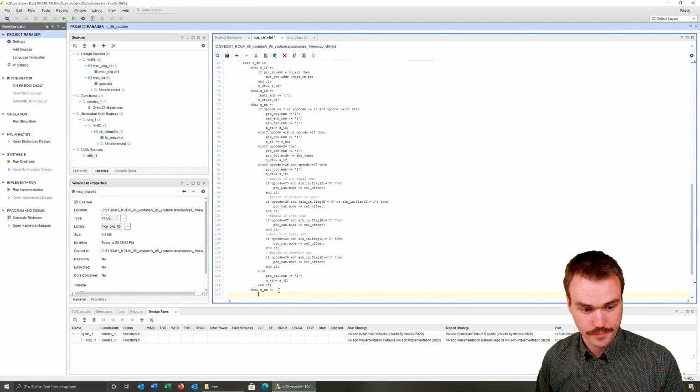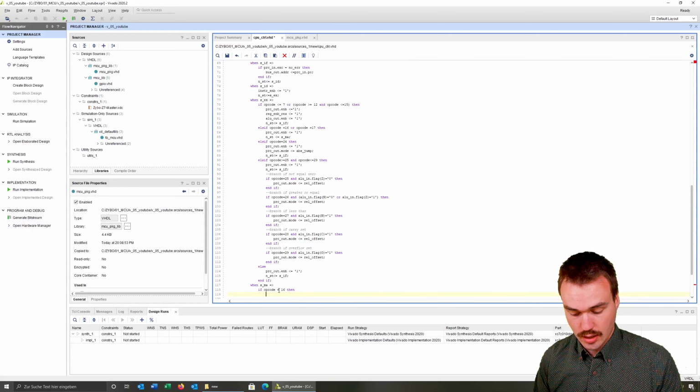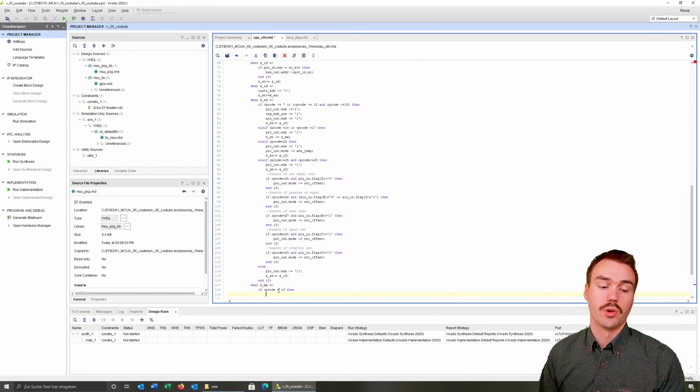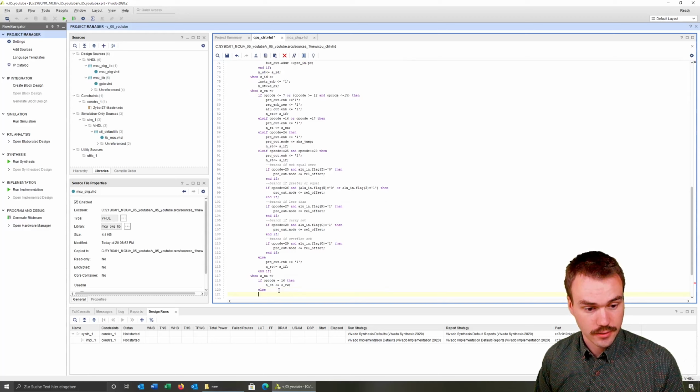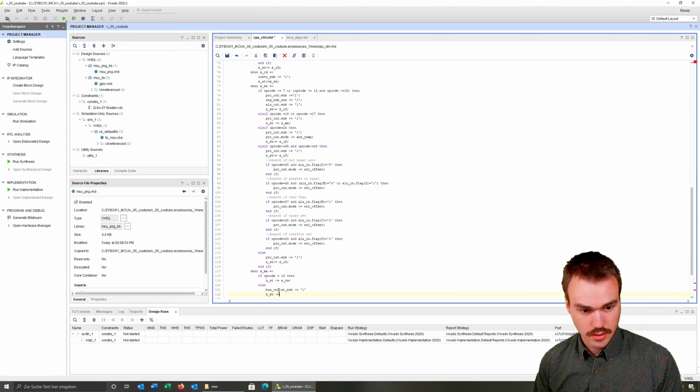Then we want to do the following: if the operation code is equal to 16, then we know it's a load instruction, and we want to have also the last step, so we can say next state is equal to state register write back, and else pass_out.write_enable is equal to 1, and the next state is equal to the state instruction fetch.